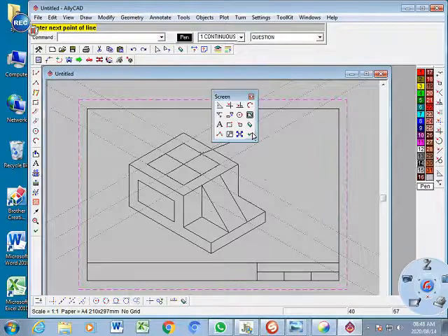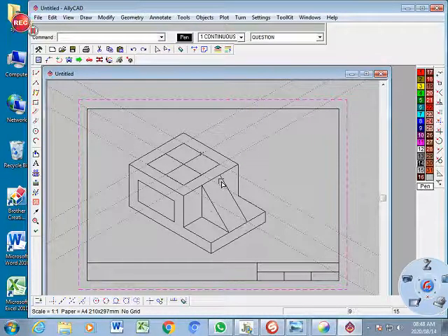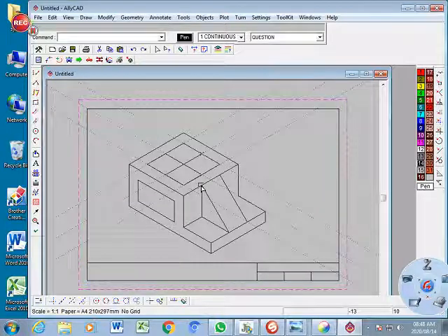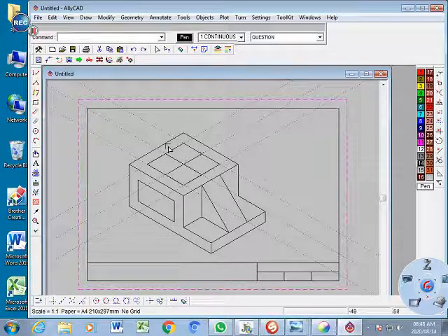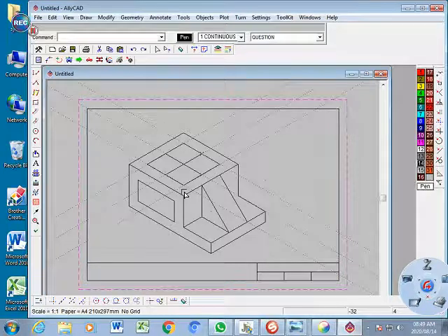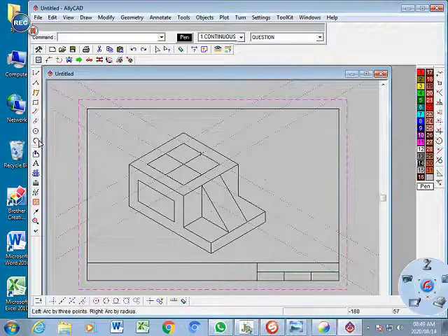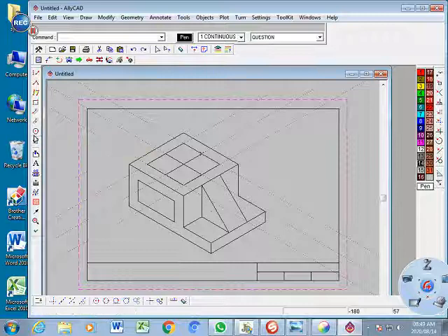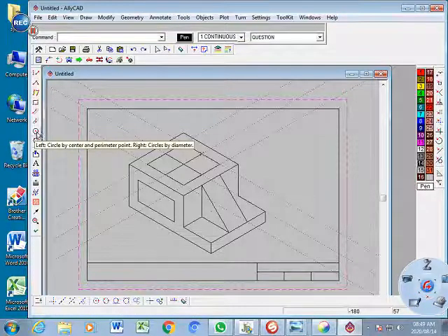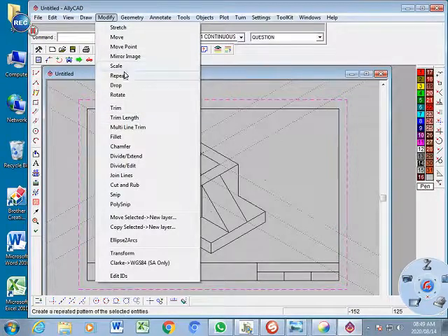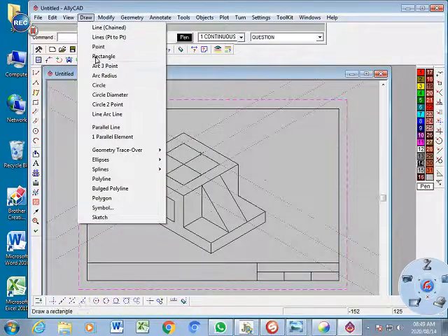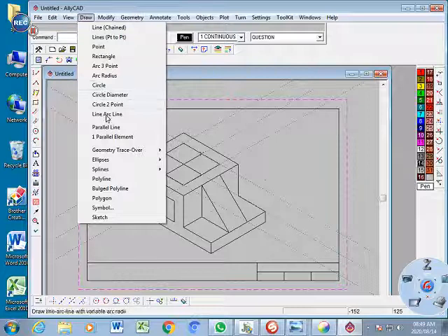But when you're in the computer program, you actually don't need to put in all the steps that we normally do when we draw with drawing equipment, because you just need an oval that will touch in that space here, so you don't have to draw the V and the crossing there. It's not necessary for that. All you have to do is go to modify, and you can go to draw, and you can go to ellipse.